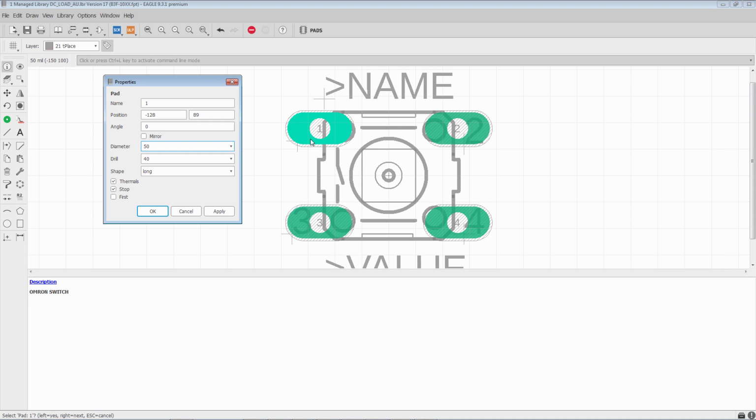So if you have small annular rings or very thin annular rings, what you will probably find is that when you use the part, the rings will swell. It's because the design rules are set in such a way that they've turned out to be larger than the diameter you specified. At that point, you would go into the design rules, annular ring tab, and make adjustments. We'll leave it here on auto for now.